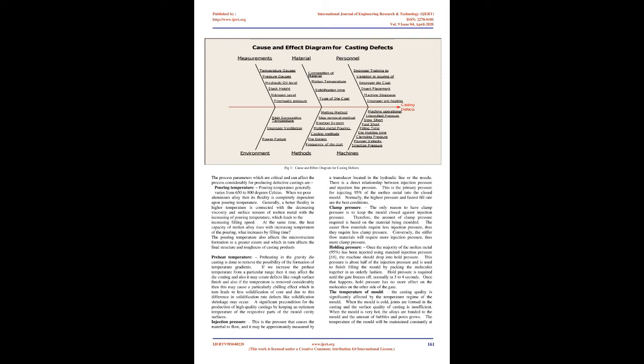8. To improve the mechanical properties of aluminum alloy parts, the semi-solid die casting process is used in the manufacture of automobile components. Semi-solid die casting has a different die structure from those of general die casting and squeeze casting. The oxide skin produced during the reheating process will cause defects when it fills the die cavity. In semi-solid die casting, the most important factors are the filling velocity, the area of the gate, and the position, size, and number of overflows.